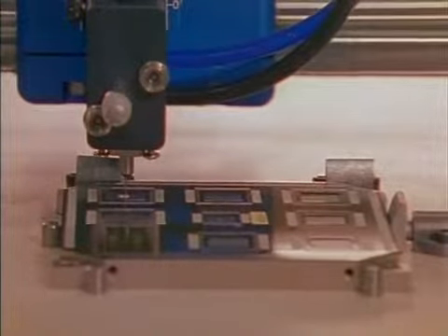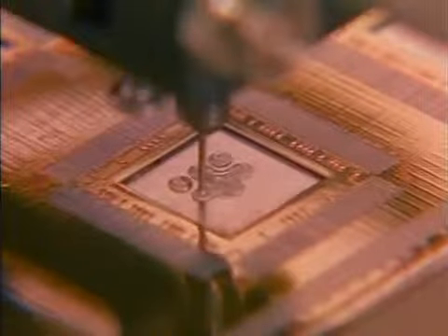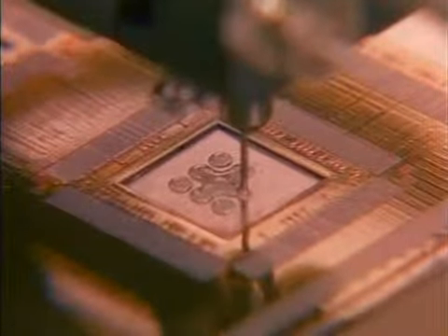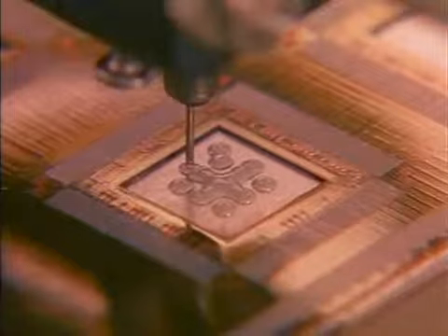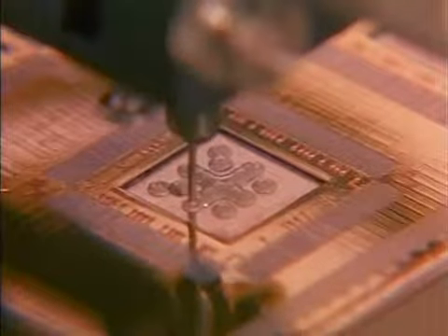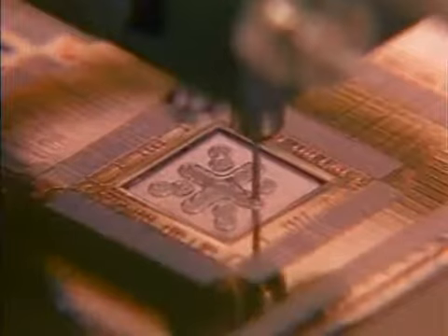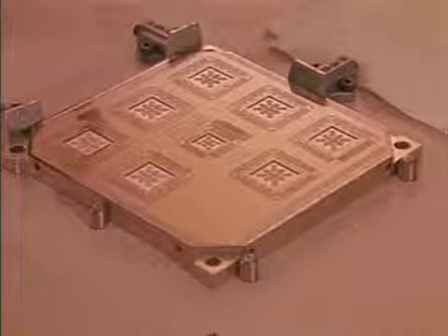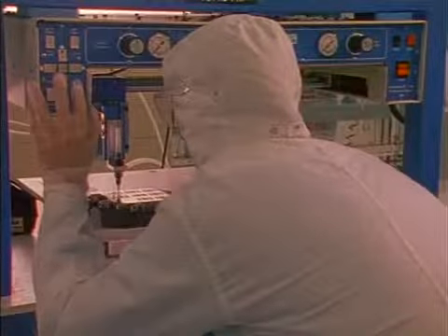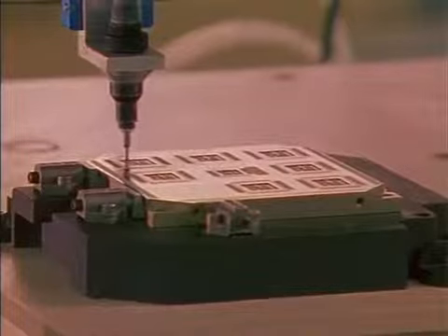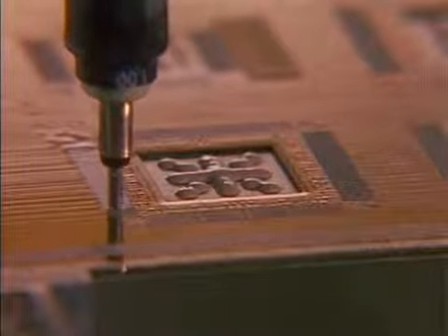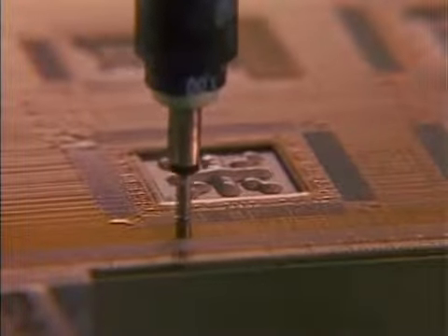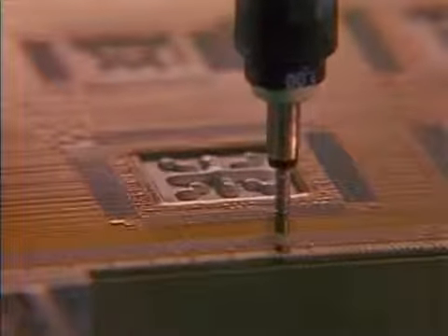Non-conductive epoxy is dispensed in each of the die side cutouts. The epoxy is filled with microscopic diamond particles which conduct the heat away from the die, while the die remain electrically isolated from the substrate and from each other. Flux is then dispensed to the solder bonding pads of each die side area. When heat is applied during bonding, the flux removes surface oxides. This enhances reflow of the solder.